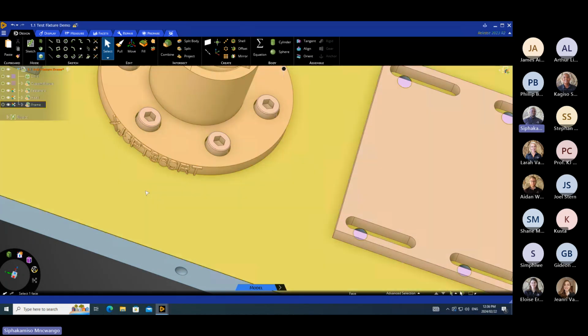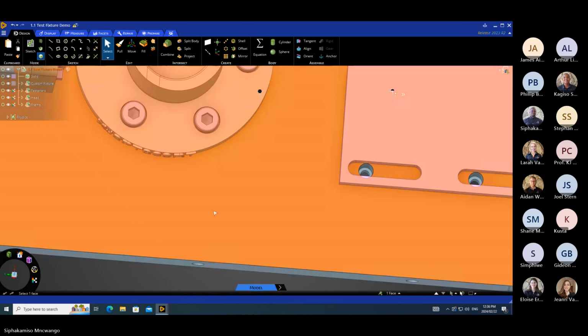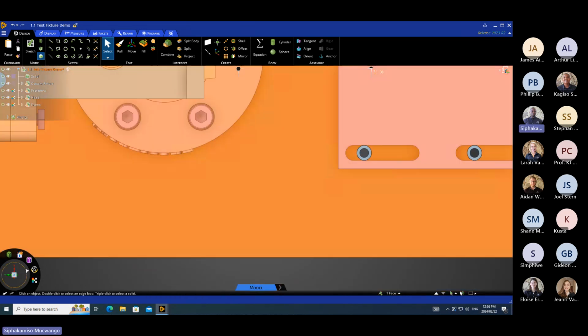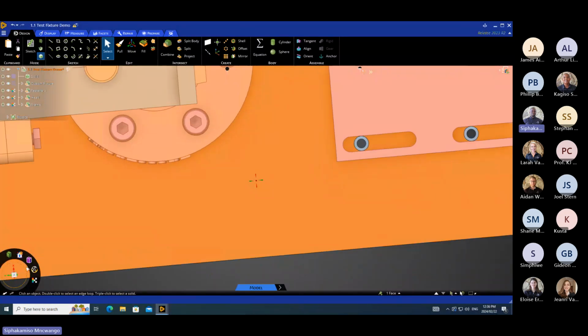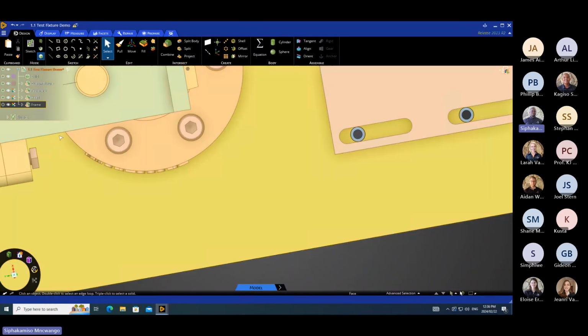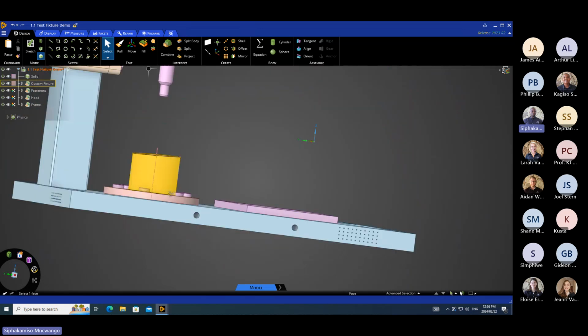The other useful thing is we can go to plan view, and then we can rotate our geometry using the view arc here on the left. And now it's easier to box select the writing here. Once we've captured most of it, press F, and that will get rid of all the writing.